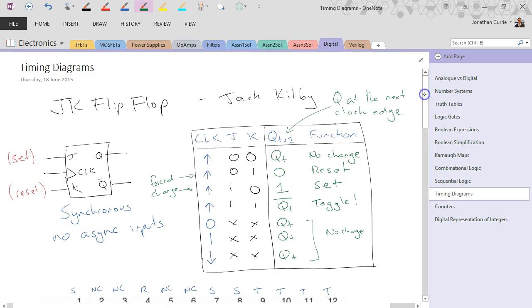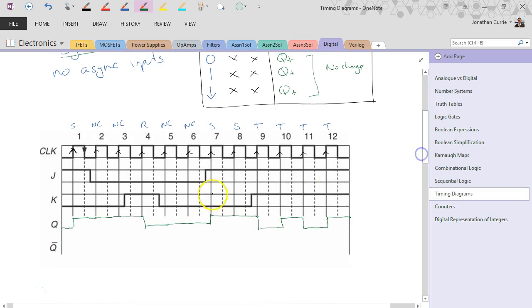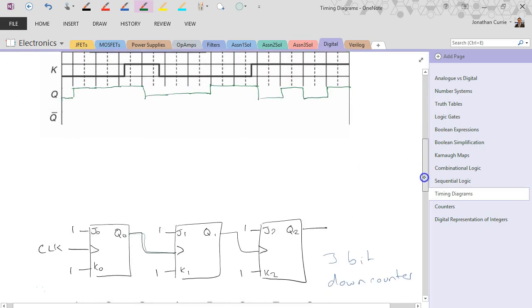Alright, so brief summary again, looking at timing diagrams with respect to our JK flip-flop. Okay, JK flip-flop, just remember the J is the set, and the K is the reset terminal. By default it's synchronous if we don't see any other inputs in it, and we get this operation here. In this case this one, because there's no bubble here, is rising edge triggered. J function is the set, K is the reset. If they're both high, and remember this, we get this toggling operation, and if they're both low, no change, it remembers it, being a sequential device, and we did work through that example here.